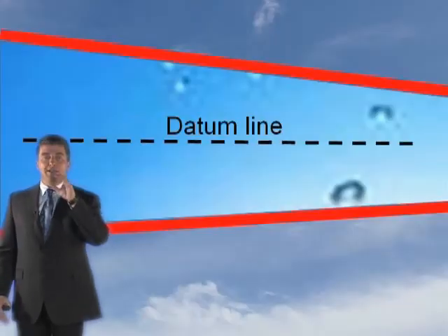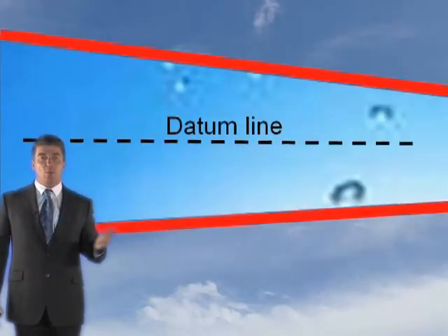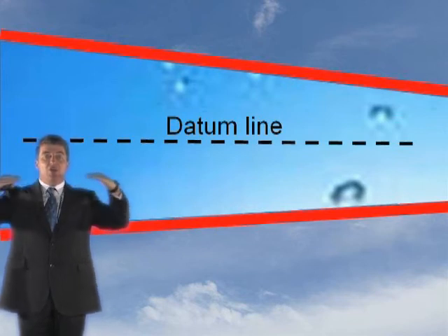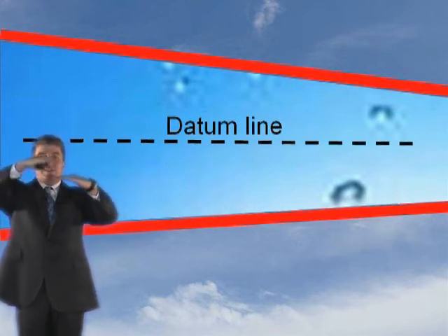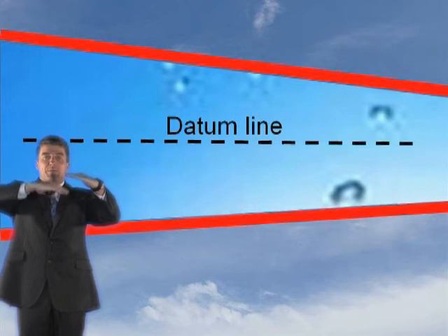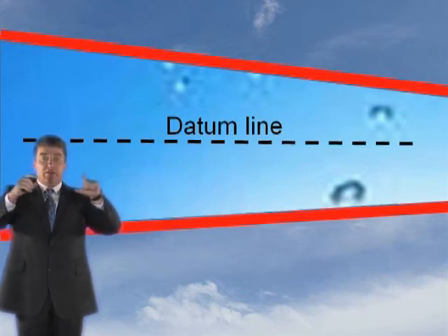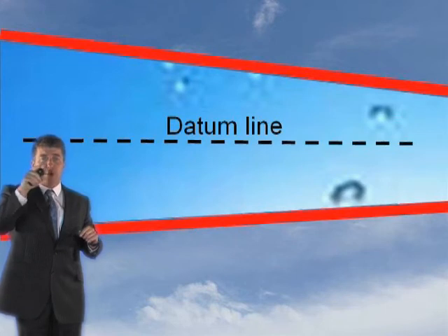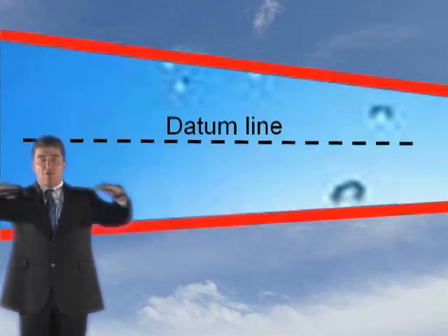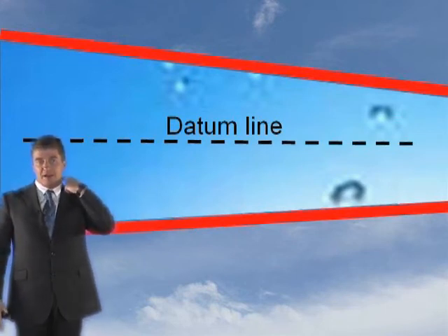Tip 3. You've got to place a datum line from where you're taking all the energies from. Wherever you take it from, it doesn't really matter because it will still work out, but it's got to be a straight line, a datum line. Now, if it's a horizontal pipe, always put the datum in the middle of the pipe. Why? Because the potential energy is zero at both points. Do you see what I mean? There's no potential energy above and below, it's the same. So if you've got a horizontal pipe, always put the datum line in the middle of the pipe.